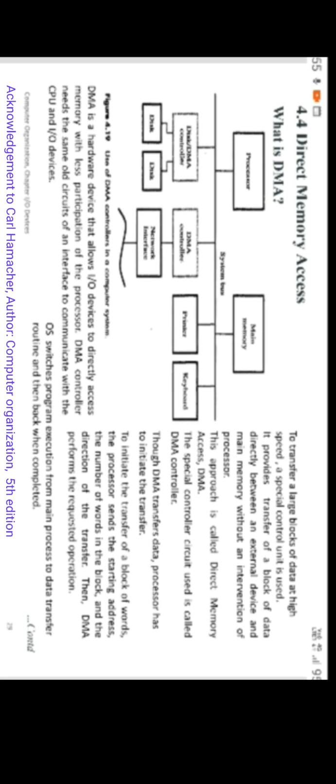Whenever high-speed data is coming over the network through the network interface, it enters and is stored in the DMA controller buffer. Now if it is to be transferred to main memory, the DMA controller requests permission from the processor. Once the permission is granted, the DMA controller gains control over the system bus. It becomes the master. Now the whole of the data from the DMA controller is transferred to main memory and stored there. This is called a memory write operation.